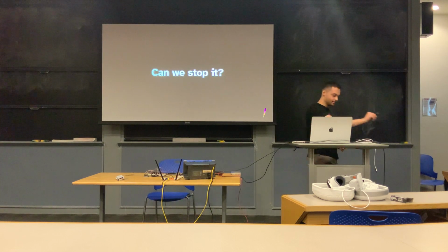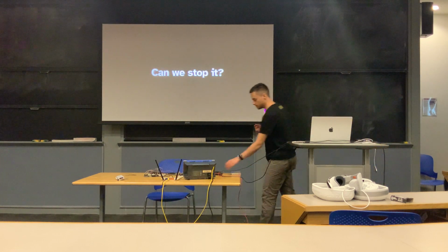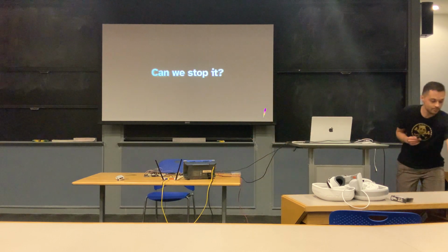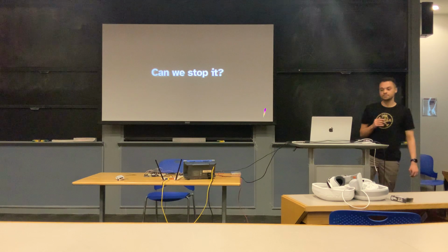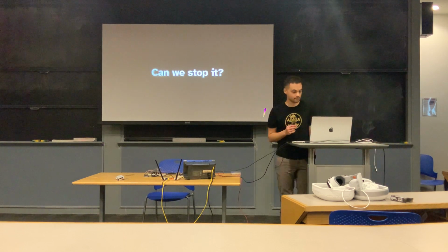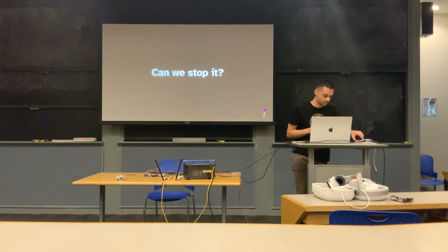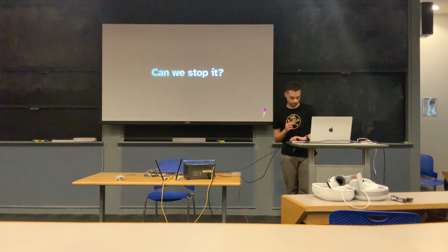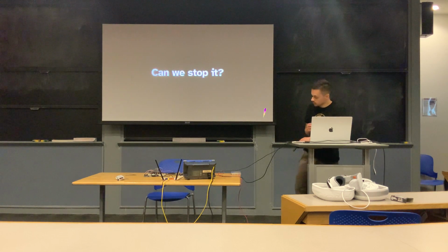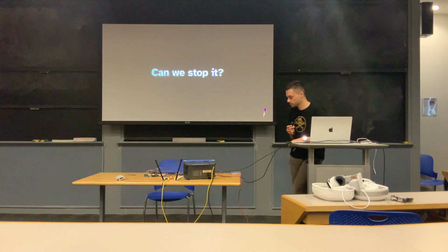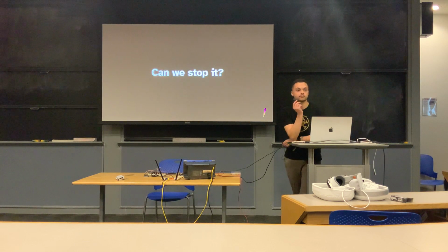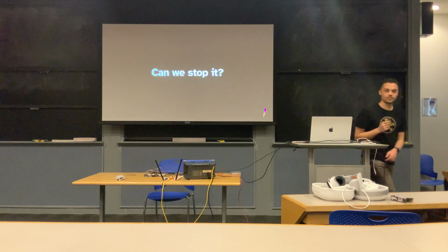I can also add a little to relate this to the last lecture. Remember we talked about secure boot. You need to check whether the hash of your boot procedure matches a precomputed hash, and you can imagine that comparison is an if condition. If you glitch that point, then even if the hash does not match, you can go to the wrong branch and assume the hash matches. So fault injection can be useful in this case, but of course you have to time it perfectly to glitch the specific point when you compare the hashes. Does that make sense?